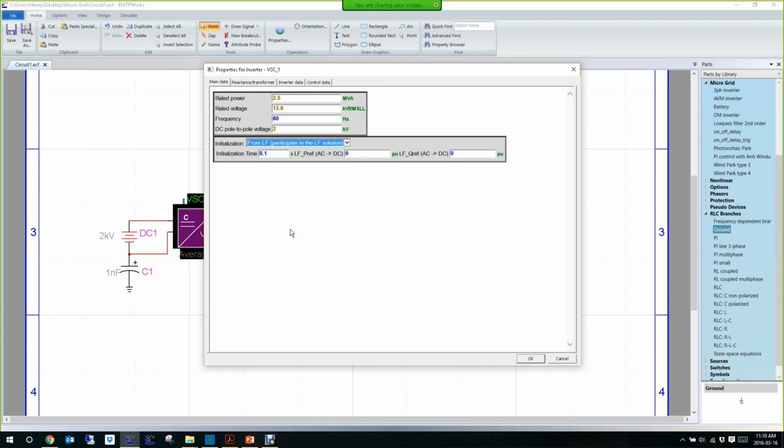I will come back a little bit later on the load flow in EMTP, but just to let you know, EMTP is a transient software, but we can do time domain simulation as well as load flow, which you will see can be very convenient in case of microgrid where you have a lot of different load and power sources. Okay, so in the load flow here I have a power reference.